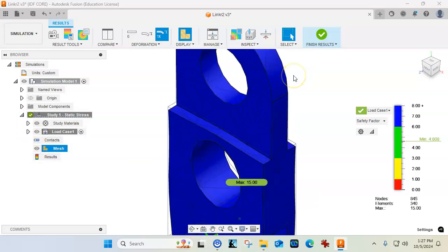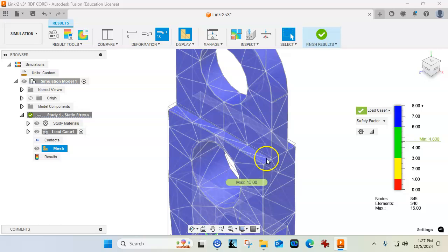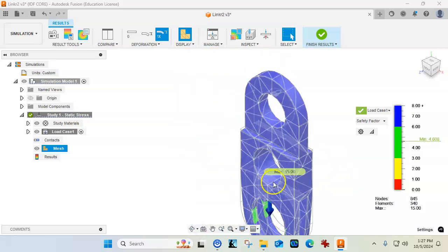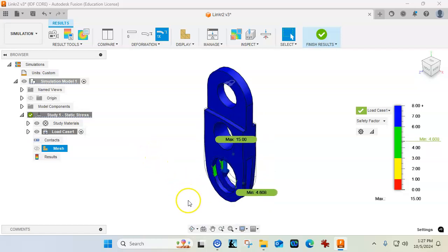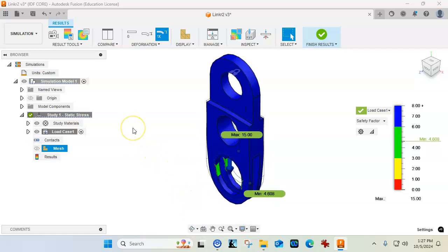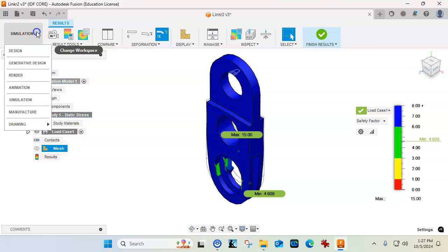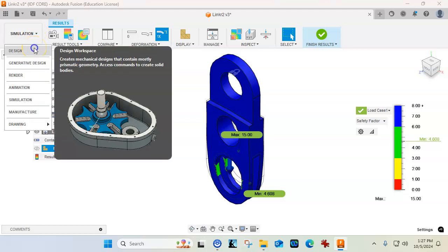The mesh is pretty wide open for computing time. An open mesh will process a lot faster. And then as we refine, and want to go through and notice stress risers and geometry that is problematic, then we could refine it a little bit more, make another pass, and get some more information out of it.